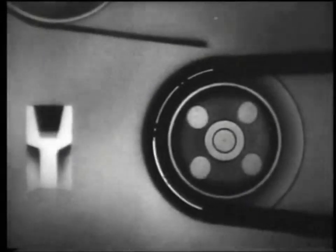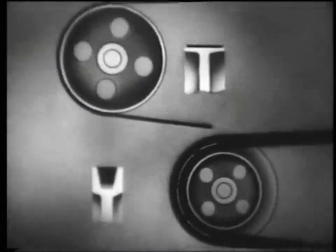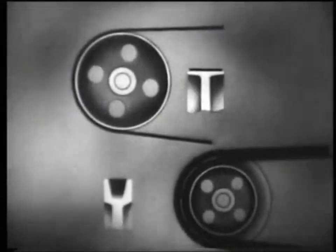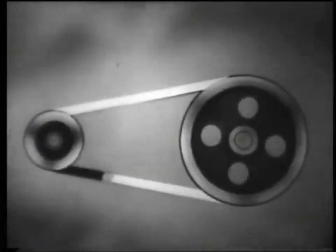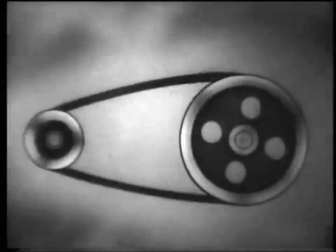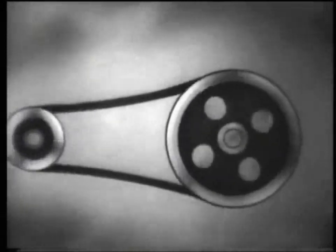However, due to the large power losses due to belt bending, the efficiency of the V-belt drive is lower than that of the flat belt drive. The possible variability of the cross-section dimensions along the length of the belt causes fluctuations in its branches and torsional vibrations of the driven system.